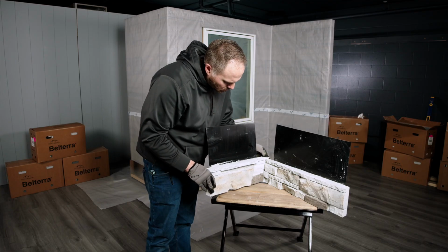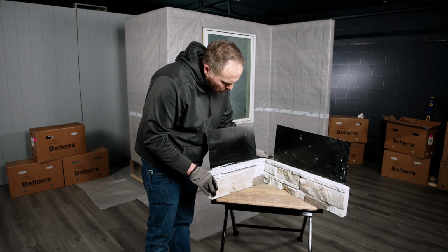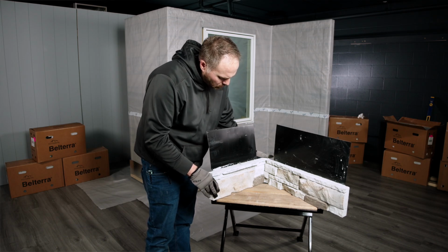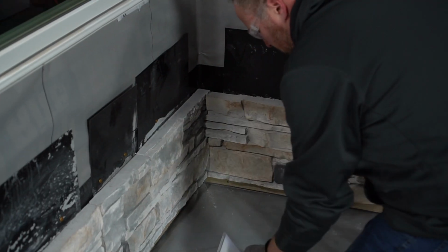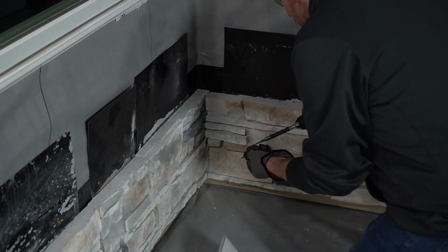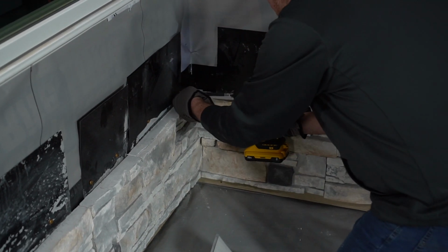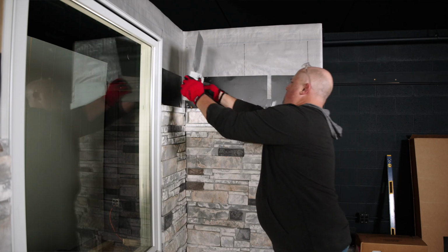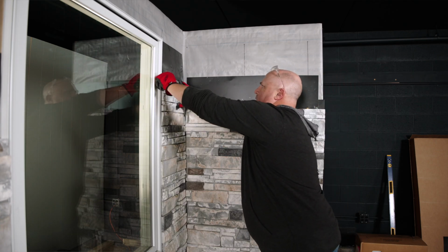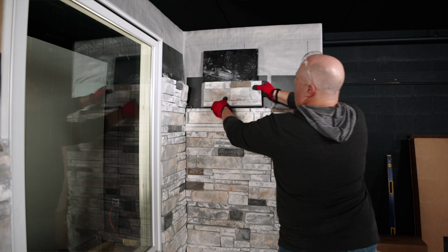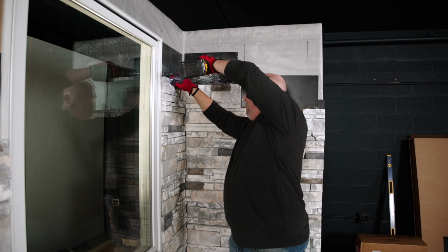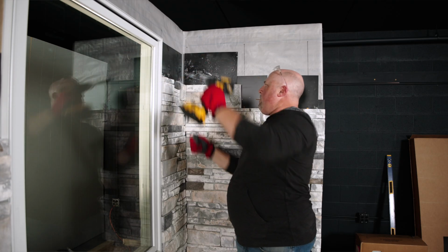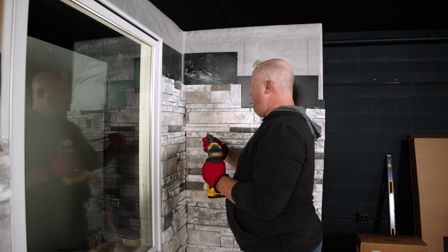Inside corner applications can be installed using 2 options. The first option is by using the 2-piece corner system and turning them for an inside corner installation. Based on the thickness of the panel's face at the corner, the tongue of the corner may need to be trimmed to make a tight fit. The second option involves miter cutting 2 flat panels slightly less than 45 degrees to the required lengths to fabricate the inside corner. Dry fit the mitered pieces and trim the mitered edges until you are happy with the fit.